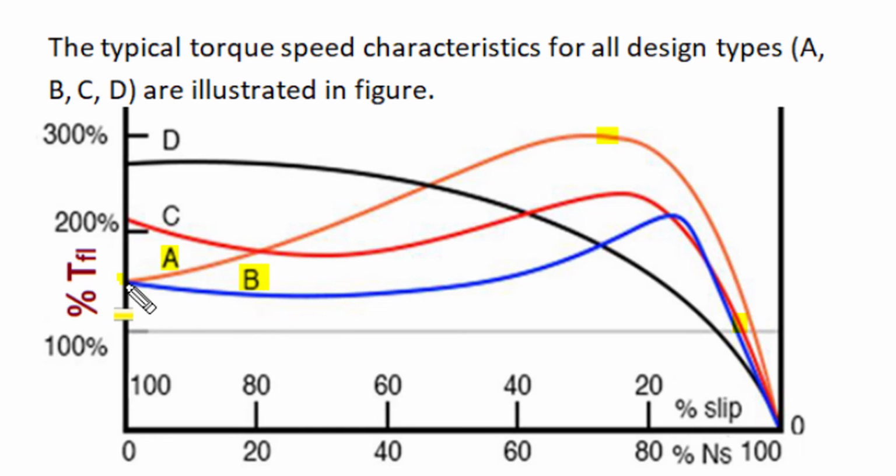it can produce starting torque 1.5 times of full load torque. Now it got a little higher leakage reactance, so its maximum torque capability is just 2 times of full load torque, and again running performance is very good, and full load slip is just 2 to 3% and it has very good high running efficiencies. Whereas NEMA design C is a double cage motor which produces very good starting torque, 2.5 times of full load torque with reduced starting current, and it also possesses good running performance and high efficiency.